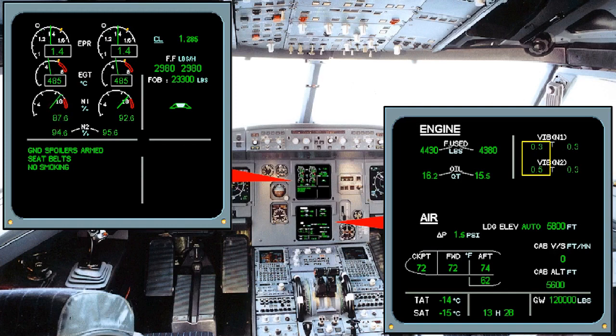An increase in the vibration level of the engine, which can generate noise, which may become audible in the cockpit, depending on whether the engines are wing-mounted or rear fuselage-mounted. And an increase in the exhaust gas temperature, otherwise known as EGT.